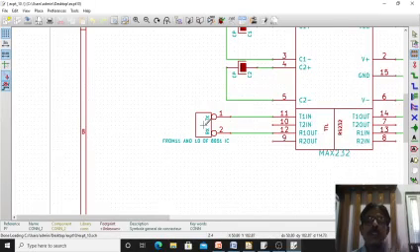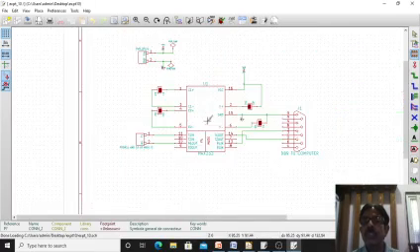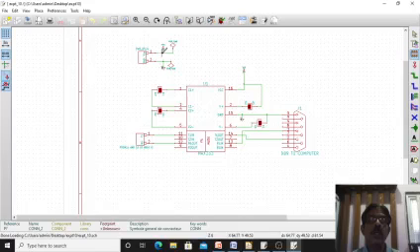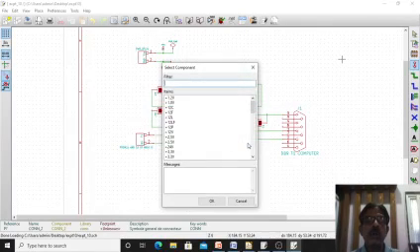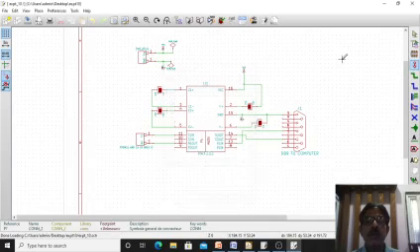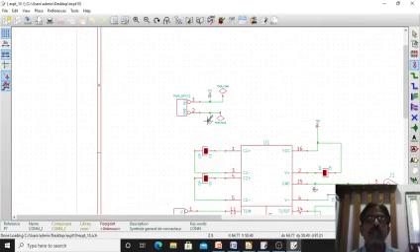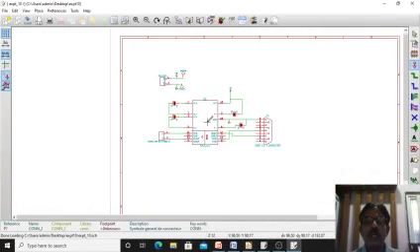So collect this, edit its name. I have given the name as TX and RX. These 2 pins are connected to pin number 10 and 11 of the 8051 microcontroller. So in this way I have collected all the components, that is VCC and ground. You know, they are present in this power flag, place a power port. In this you click here, then say list all, VCC is also present, ground is also present, power flag is also present. Collect all those, and then okay, arrange these according to the circuit diagram.